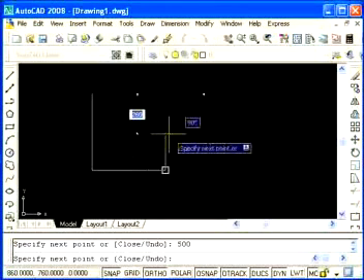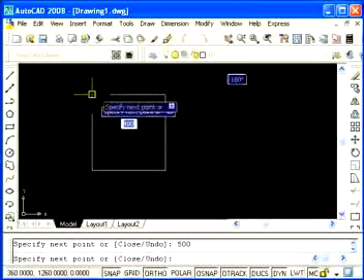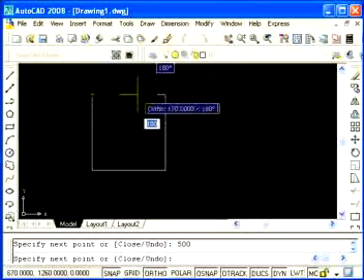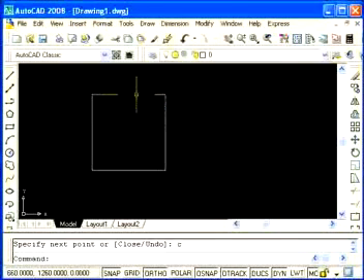And now that we've got three sides of the square drawn, we can actually either go over with the cursor and close it manually, like that, and just click there, or we can just type C and enter, and it will close it for us.